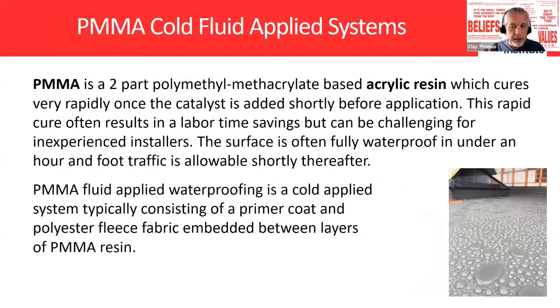Still okay, Glenn? Yes, sir. Okay. What happens is you may have 25 minutes to use it at 75 degrees. If it's 100 or 105 degrees on the roof, that may be 10 to 15 minutes. So you've got to be careful. And when you first mix these things, don't mix a lot of them, because they're going to get hard in the bucket on you.